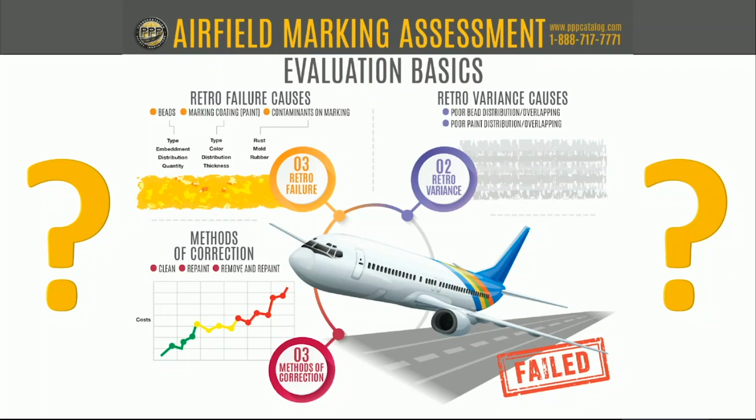A little wet mil gauge you can get pretty much at any paint store, and you just put it in there. Now be careful, you want to run over something flat, so put a panel down or something and run over it at the same speed. It's funny how people tend to change their speed when they go over a test panel, but that's a great way to test it. The next question is, how long does thermoplastic usually last?